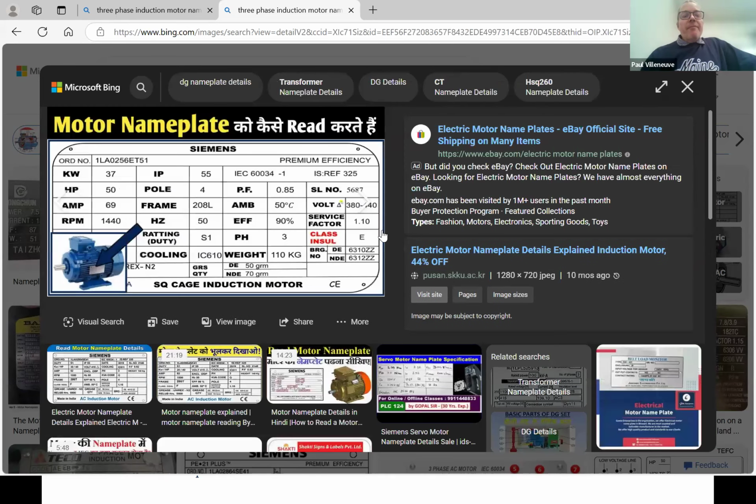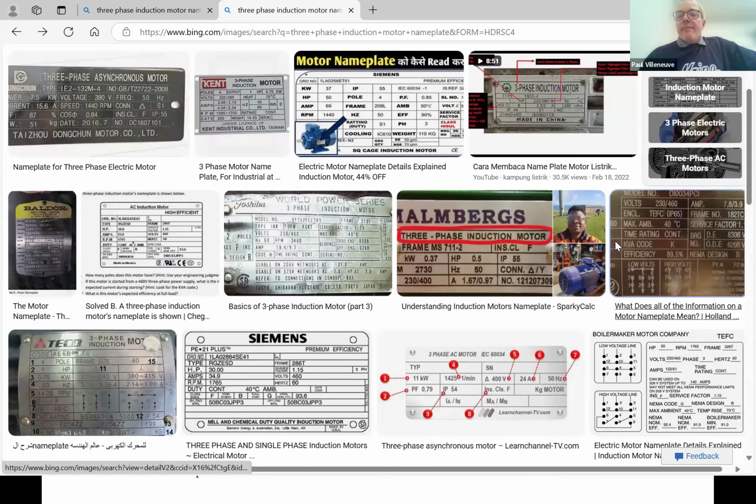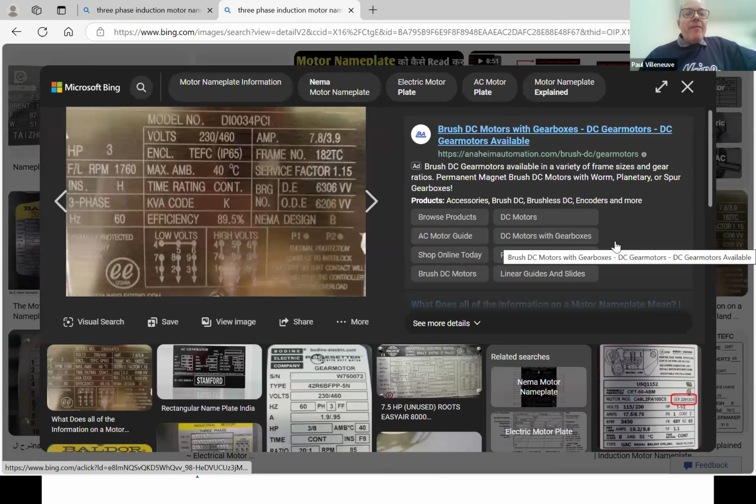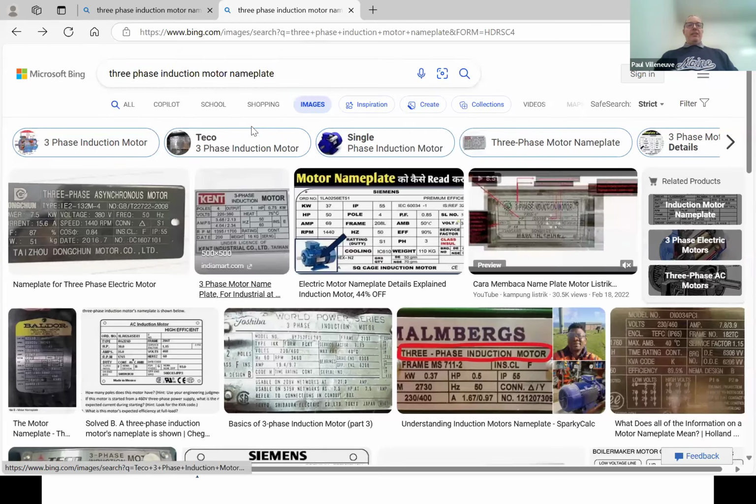Let's look at this one. Let's see, where's the speed? Does that mean it's 90% efficient? This is 90% efficient at its full load speed. This is a 50 hertz machine, so we don't want this one. Try to find one that's kind of new. 60 hertz machine. This is only 90%. That's pretty low. But this operates at 1760 RPM. So this is probably a 4-pole machine, right? That's operating darn close to its synchronous speed of 1800 RPM. Let's take a look now and modify this.